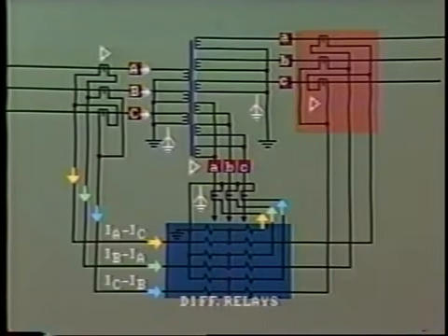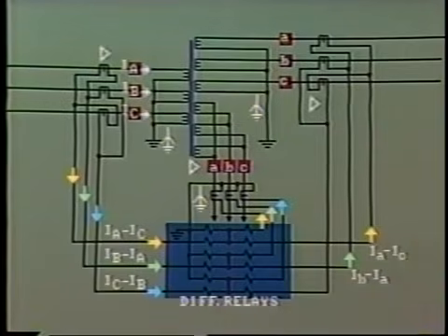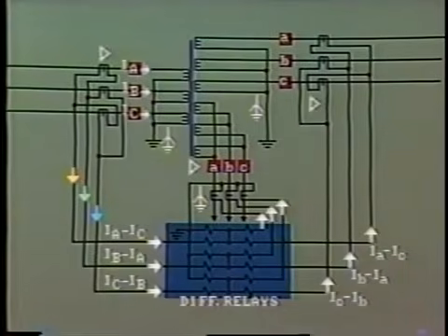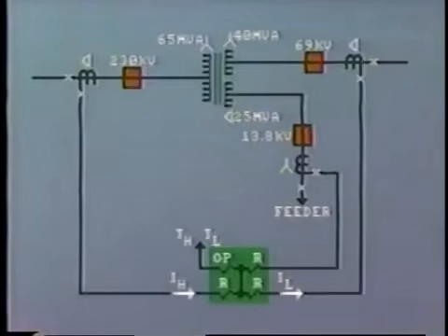Now, having checked the primary and tertiary windings, let's check the phasing of the CTs in the transformer's secondary. These are delta connected like the primary. Hence, like the primary, the currents from the relay are IA minus IC, IB minus IA, and IC minus IB. With balanced operating conditions, these three sets of currents cancel, and no current will flow through the operating coil. If an internal fault occurs inside the transformer, then out-of-balance currents flow in the operating coils, and the relay will trip. With the multi-winding transformer, selecting the correct CT taps and calculating the mismatch is similar to our earlier example.